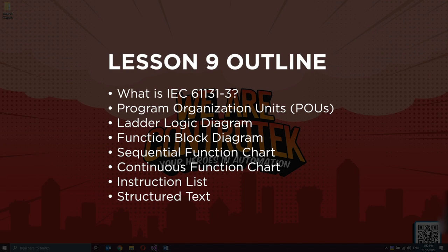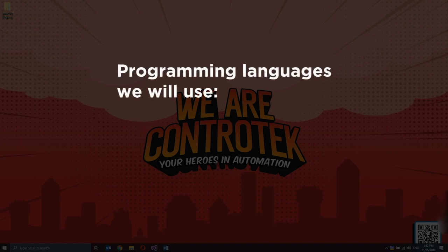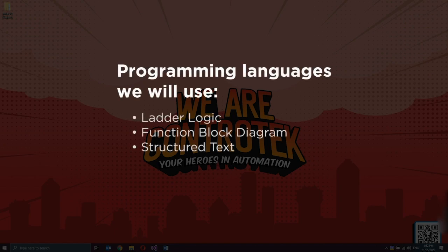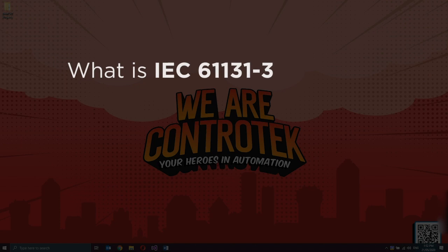For the rest of this video, I will demonstrate how to create POUs and do some programming, and I will mainly focus on the most commonly used programming languages in the industry, such as ladder logic, function block diagram, and structured text.